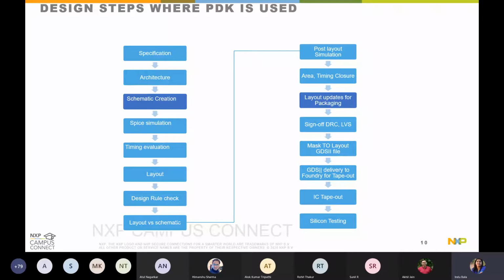Then we have the design rule check. The PDK provides all the decks for that, and the PDK defines, along with the foundry and other stakeholders, what rules need to be followed for a particular PDK. For layout versus schematic, the PDK does provide the LVS decks. Vanna will cover these decks in detail.